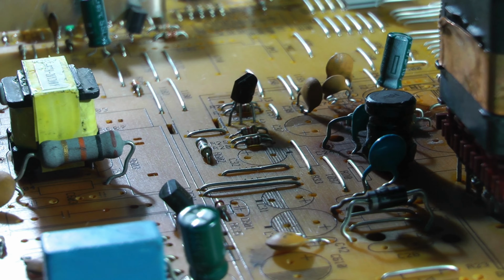For the complete project power supply, I'm using a 12-volt 2-amp transformer. The reason for using 2 amps is that I've added an amplifier module as well. If you're planning to build this project without the amplifier module, you can also use a 12-volt 1-amp adapter.